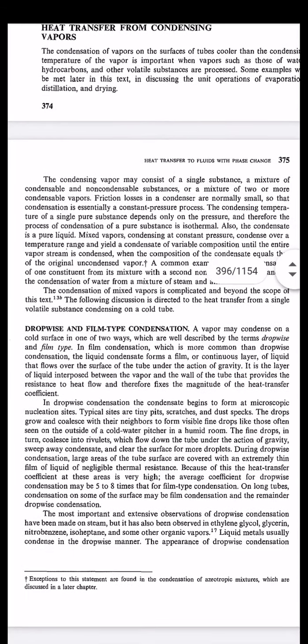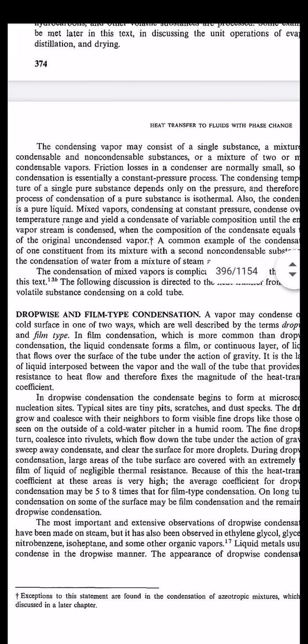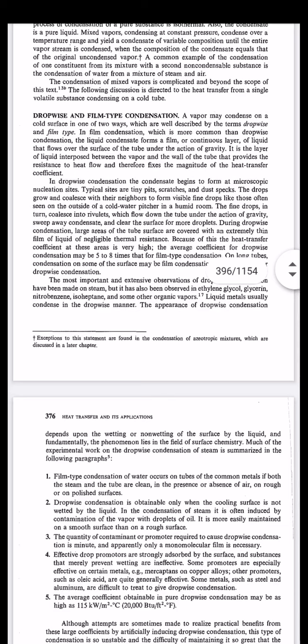So dropwise and filmwise, we have discussed both cases, and I told you dropwise is expected or desirable, but the thumb rule says it is not possible to have dropwise condensation everywhere or all the time. Now the designs are made by assuming there is filmwise condensation. Additional resistance is always considered while designing any kind of heat exchange equipment. So here the theory has been given.